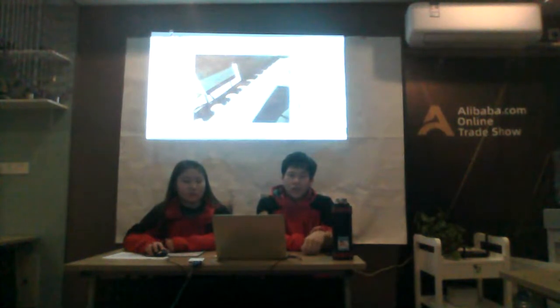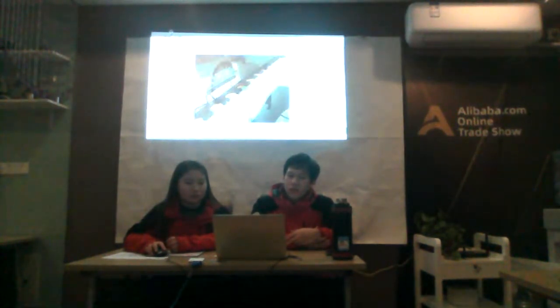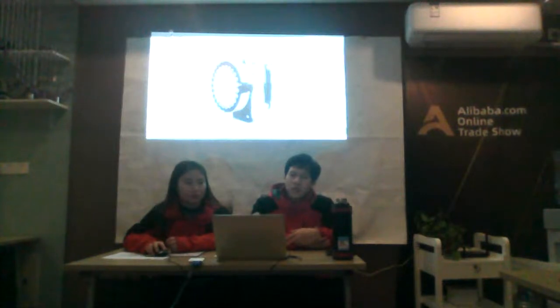And this one is the line type ATC. For this type of ATC, we usually hold 16 to 18 tool stations. And this one is the ARM type ATC, and it can hold over 24 tools on the device.